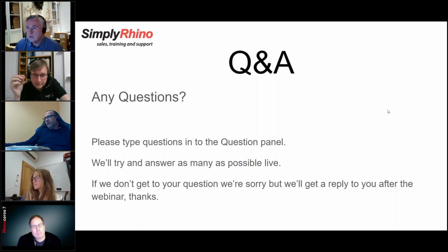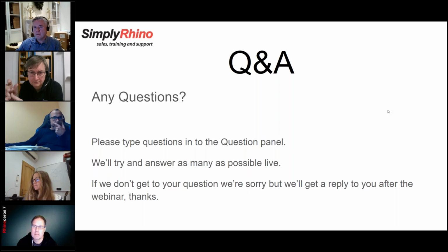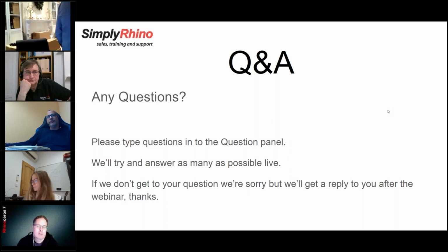Okay, so one here: does Rhino version 7 have IFC file compatibility? That might be one for Scott. Yep, that one's for me. So the answer is for base Rhino, no. For the VisualARQ product, the plugin is your IFC reader, and the reason IFC is in VisualARQ is that IFC requires essentially what we could call an expander. The IFC does not contain the geometry.